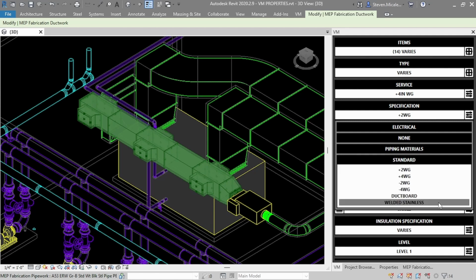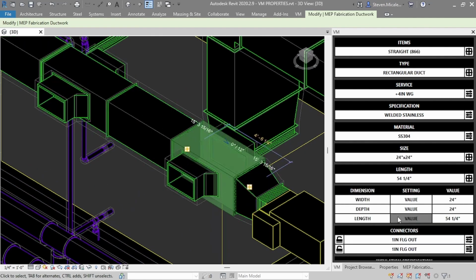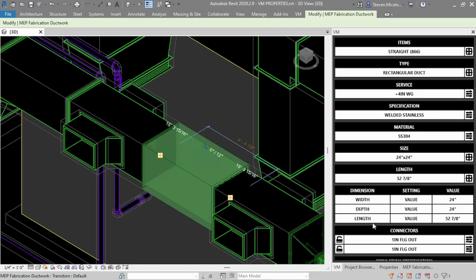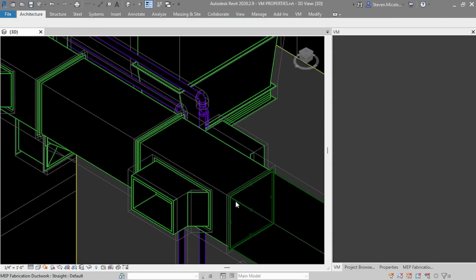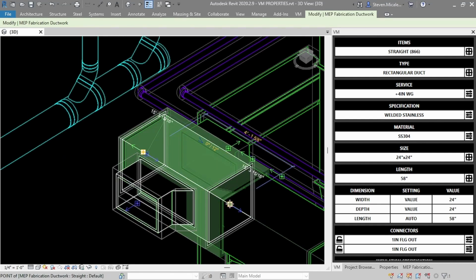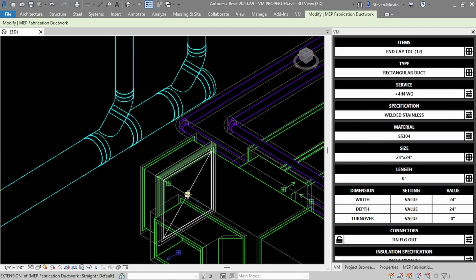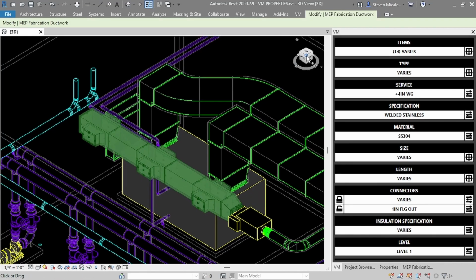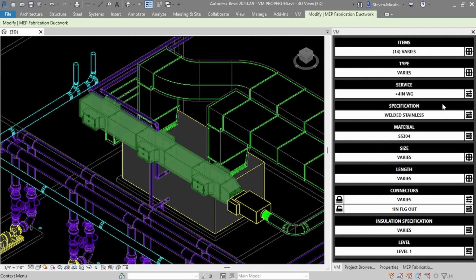with zero additional rework. For more significant specification changes, however, like changing a TDC spec to a welded spec, the parts will be disconnected and we must manually fix the mess that it makes. This is, however, a far better option when considering the alternative that Revit provides. In the event that a spec change creates an unacceptable inconsistency with the service name, we can perform a copy and rename of the specified service in the fabrication database profile, then change service before changing spec, as previously mentioned.